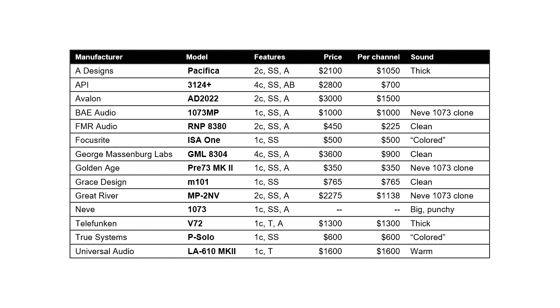Class B solves the problem by having 2 distinct amplifiers, one to amplify the positive and one the negative voltages. The disadvantage is that at the crossover between both sides, the signal may be distorted because the amplifying devices take some small time to start working. As a result, they are perceived to be less accurate than their Class A counterparts. The third type, Class AB, tries to take the best of both worlds by having the following amplifier start up before the crossover is reached, so that when it does, the distortion is minimized. As you can see, Class A does not mean that it is the best class, only that it is one design amongst others.